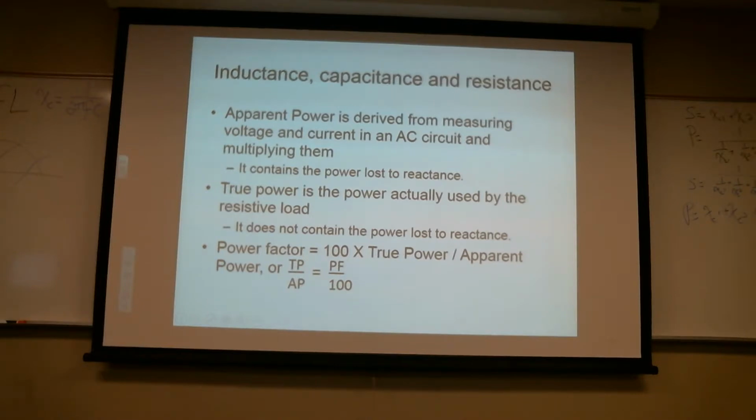So we can predict some of that behavior and try to accommodate for it by turning banks of capacitors on and off or whatever. In an airline, it's completely different. In an airline, you basically got two states of being, right? Lights on, lights off. And the pilot controls lights on, lights off. So you may have the light circuit designed to where when it comes on, being that they're big inductors, they may also have some banks of capacitors come on at the same time. It may be worth the weight in fuel savings because you're going to save that much weight in fuel savings and operational cost and all the rest of that. So it sort of depends on how controlled the environment is, and you know, how much you're willing to invest in it.